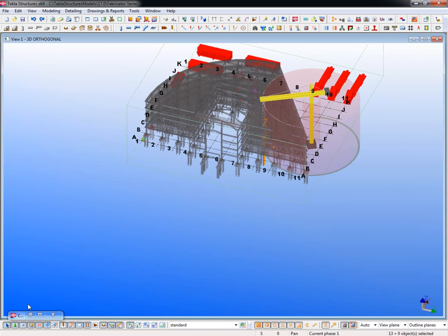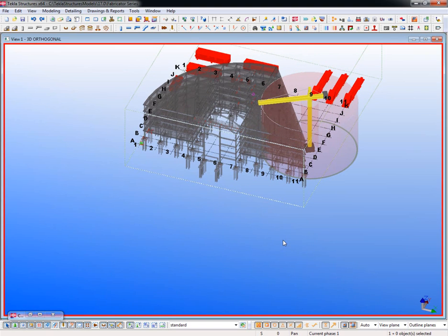So be able to again plan the specific days that you'll be able to erect these based on how that crane is actually positioned. It should be noted as well, here's a little caveat, that this is based on the proximity from the center. It's not based on any weight capacity of the crane. If the center of gravity is within the length of the boom, then it counts it. It may be that there's a heavy object at the full extent of the boom that it physically wouldn't be able to lift, but I'm afraid that's on you guys. We're not going to take responsibility for that yet. But this is the physical reach. You can look down that list or even sort that list by weight, and then check that there's nothing too heavy at too far a reach for the crane. So just worthwhile noting that.